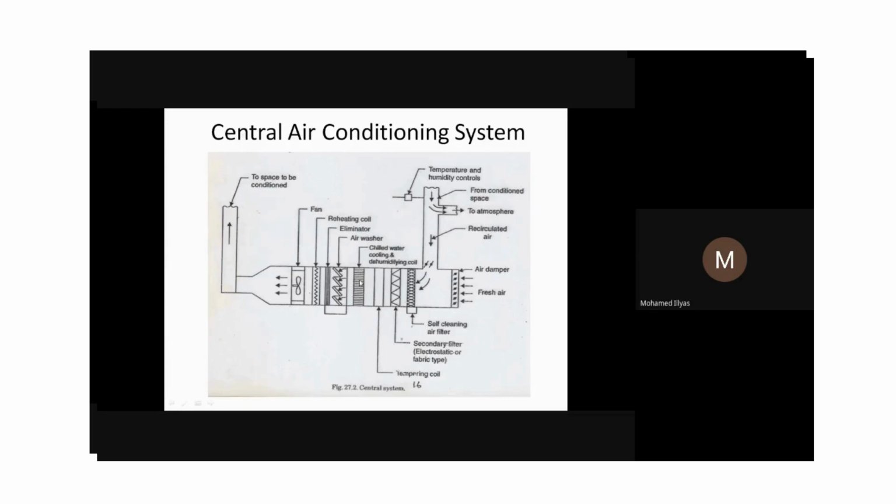So what we do here is cooling, and this cooling coil is connected to the vapor compression refrigeration system. This is nothing but the evaporator. At the outlet of the evaporator, the refrigerant comes out in the superheated state, so we ensure that it is in the superheated region.